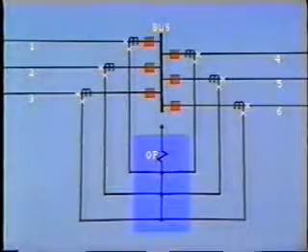As we mentioned earlier, on large, high-voltage buses, a bus fault should be cleared as rapidly as possible due to the extremely high value of current which can flow into the fault. On the other hand, the last thing we want is for the bus to clear all of the breakers for a fault out on one of the connected circuits. What we need is high-speed differential protection which is reliable. Let's look once again at an example of simple current differential.